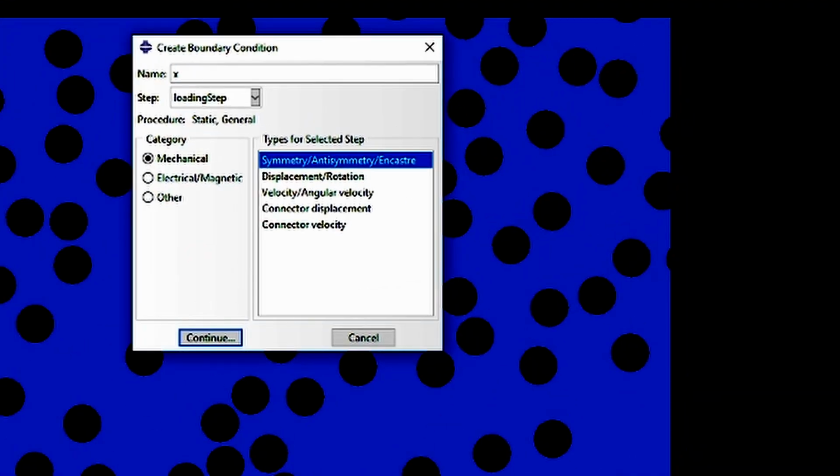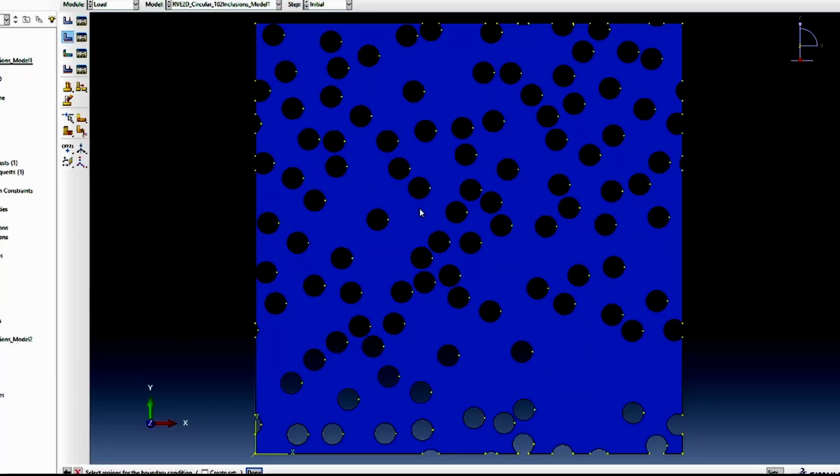I'm going to do a tensile test simulation on this. So my X back would have to be a roller support. Remember, we're going to use periodic boundary condition. The method of the periodic boundary condition I'm going to use only allows you to apply boundary conditions on the corner nodes. The spaces in between will be implemented with periodic boundary condition, using a software that again I've developed.